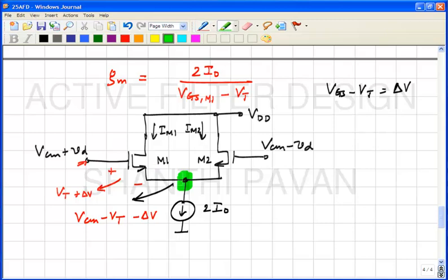Please note that this voltage can never be higher than this potential. Correct? Okay. I mean, physically, that means that the transistor must be off. M1 and M2 will be off then if the source is higher than the gate. So you should never stutter when the source voltage, even if you have some crazy doubt as to whether it is VCM minus VGS or VCM plus VGS.